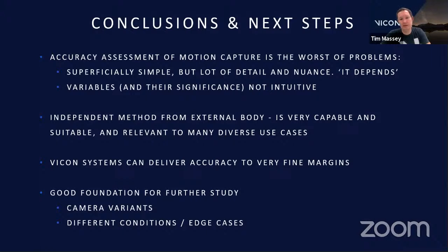The external wall, one side of the volume, was heating up and cooling down and moved a lot more over a 24-hour period than the internal wall, because of the temperature changes on the other side of the wall, which is really interesting and is not something that would be immediately obvious. Obviously, some of the variables are more intuitive than that.